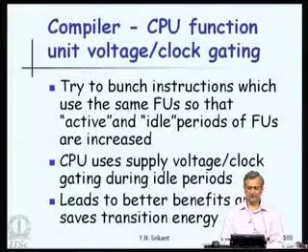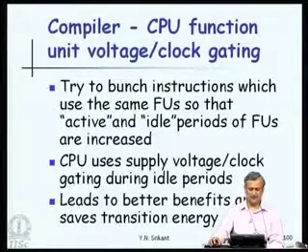So, the CPU uses supply voltage and clock gating during these idle periods, that is done by the hardware, whereas the rearrangement of instructions, so that the instructions which use the same function unit are bunched together, is done by the compiler. So, this leads to better benefits and it saves transition energy in the CPU as well.